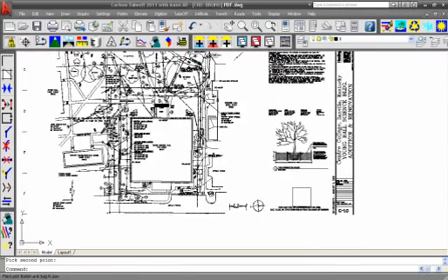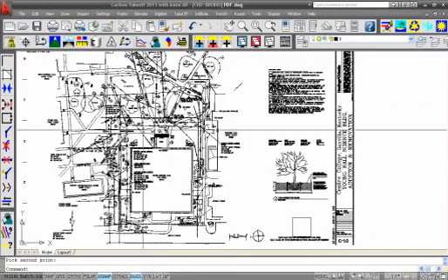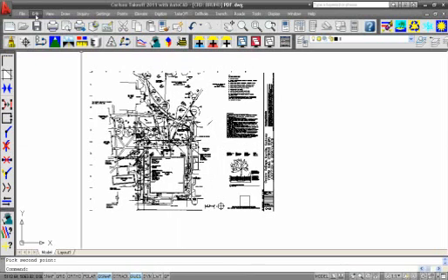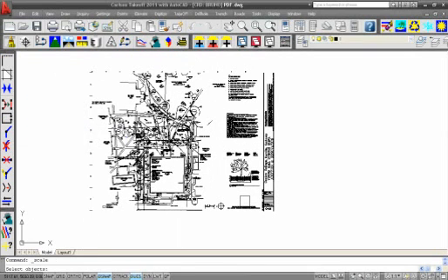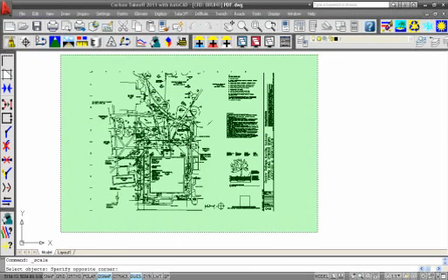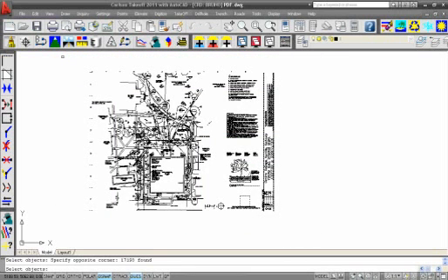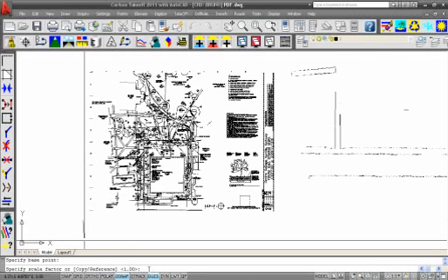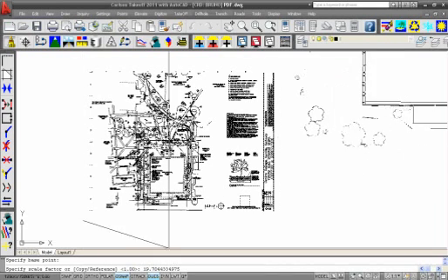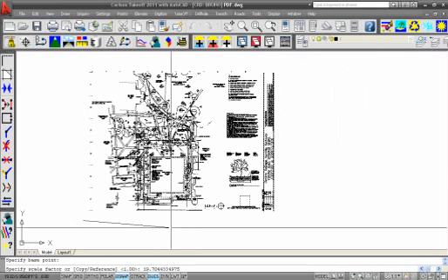The 2D scale can take a long time on a drawing this complicated to convert it. So I'm just going to use the AutoCAD scale and use that factor. Okay, select objects, base point, and paste in that value. Okay, and hit enter.